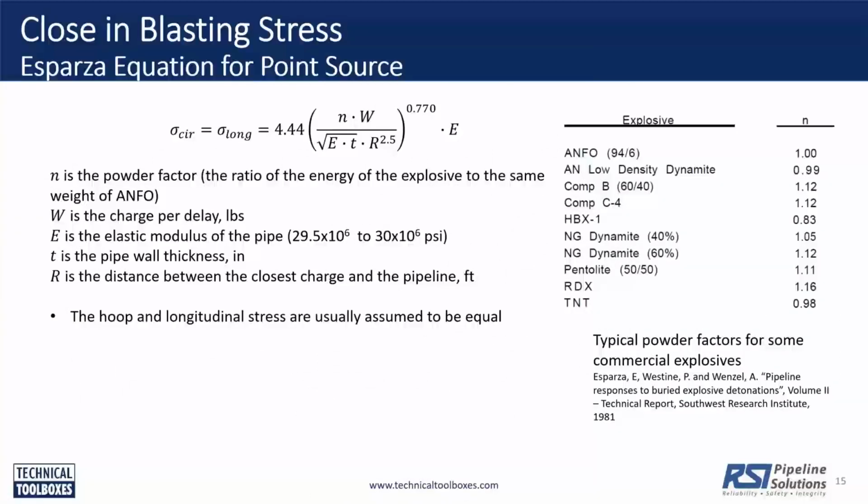The output from the previous equation was the peak particle velocity, or the radial velocity. They are almost equal. Peak particle velocity is the parameter that blast contractors usually understand and deal with. For example, they say the peak particle velocity near a structure should be less than 2 inches per second, right?